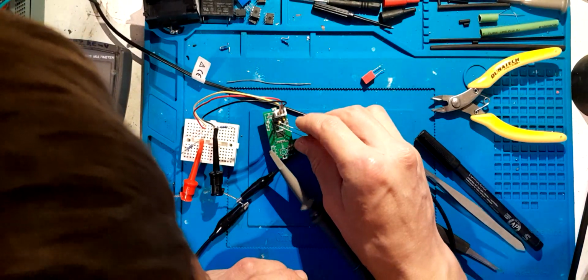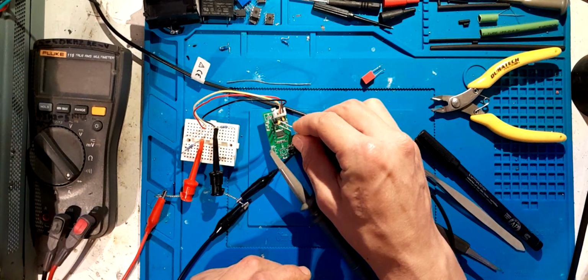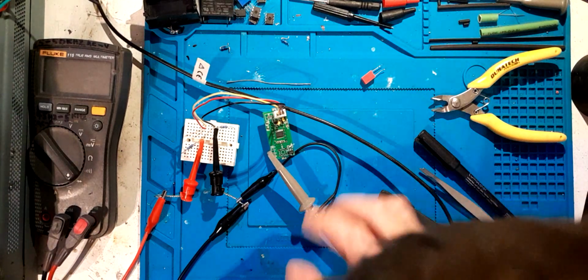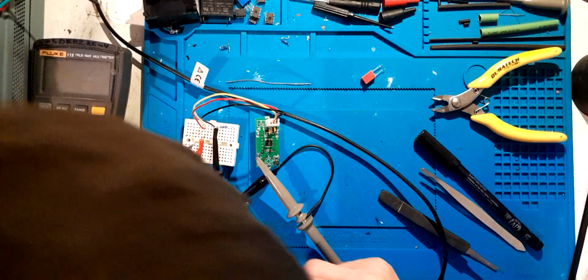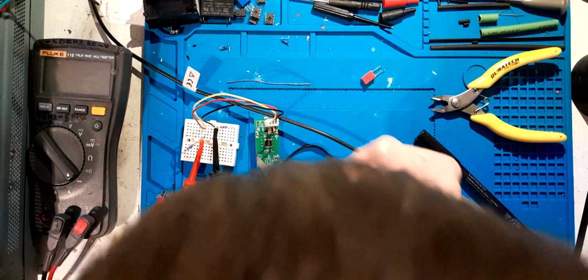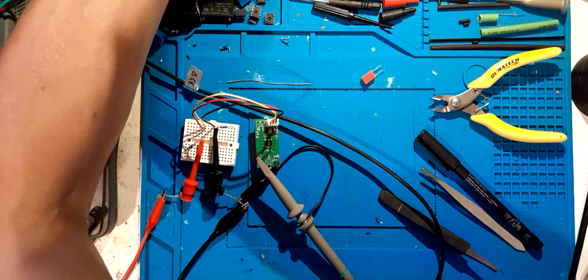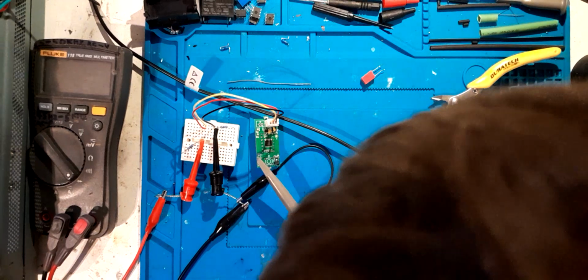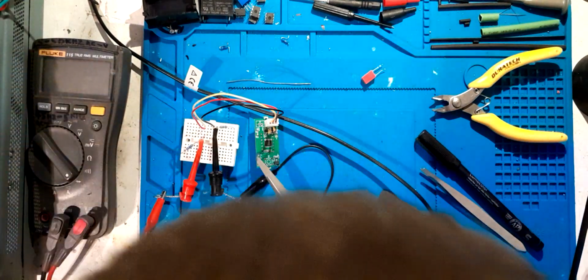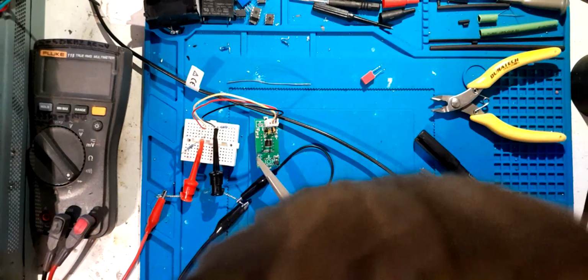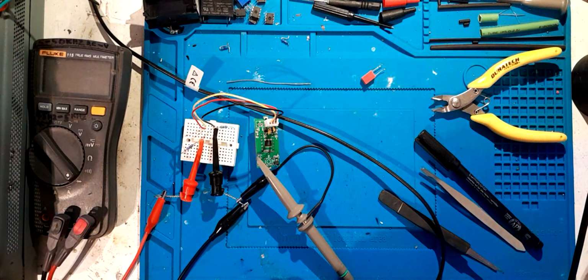Now what about the one that's closer to the micro? Actually has the same effect. You'd think it would have more of an effect. So apparently me upping the capacitor that was there originally, which was 100 nano to 1 micro, has done all the job you can do for getting rid of the high frequency noise that was just around the micro's positive line. This bulk capacitor, I'd say the noise goes away by half by adding another 10 microfarads.